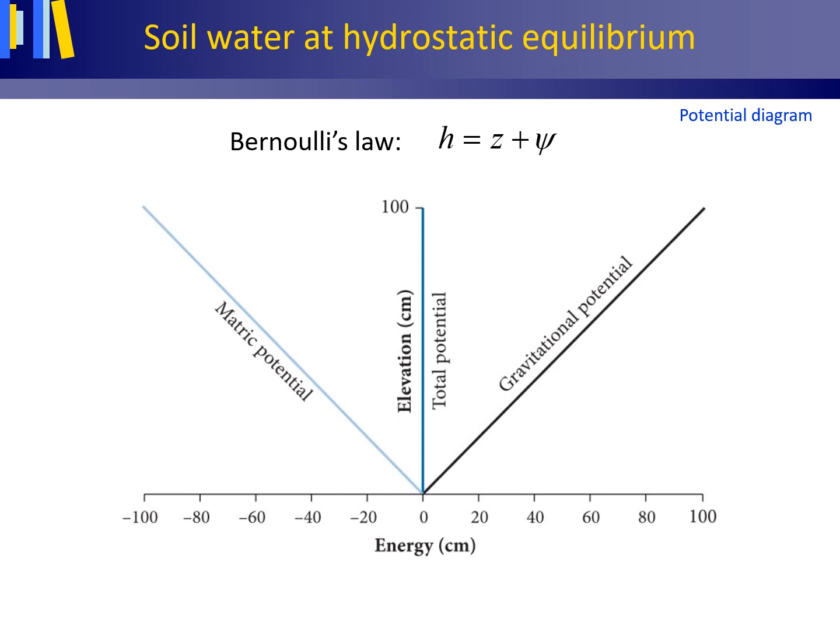Now let's extend the hydrostatic equilibrium, no vertical water flow, into the unsaturated zone. What would a similar graph on the hydrostatic equilibrium conditions, no water flow, look like in the unsaturated zone, the zone above the water table? The soil pores then generally contain both water and air. In the unsaturated zone, as a consequence of Bernoulli's law, also the total energy, or another word for this is total potential, equals the sum of elevation head and pressure head.